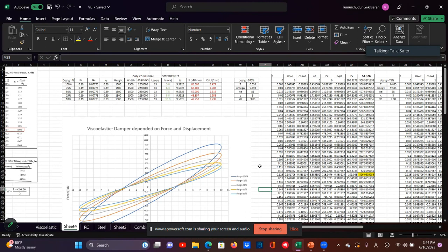It depends on the earthquake. For example, if we assume 9 millimeter for the target deformation, the real deformation will be larger. Actually in real practice, I think you put this one based on the test displacement, which is very small. But if we check papers that applied it to real buildings, usually displacement is around 50 mm to 60 mm.